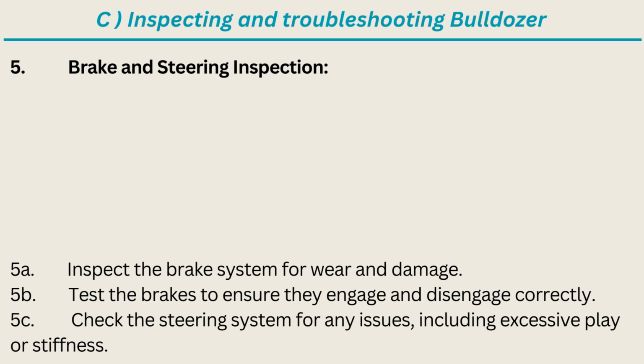5. Brake and steering inspection. 5A. Inspect the brake system for wear and damage. 5B. Test the brakes to ensure they engage and disengage correctly. 5C. Check the steering system for any issues, including excessive play or stiffness.